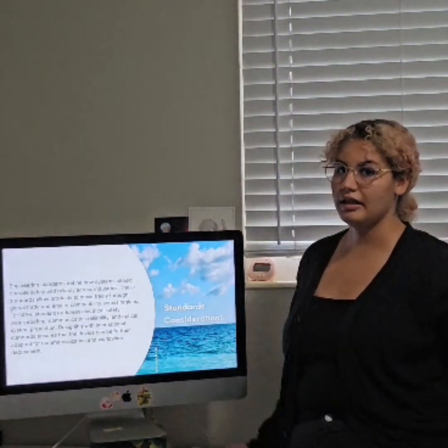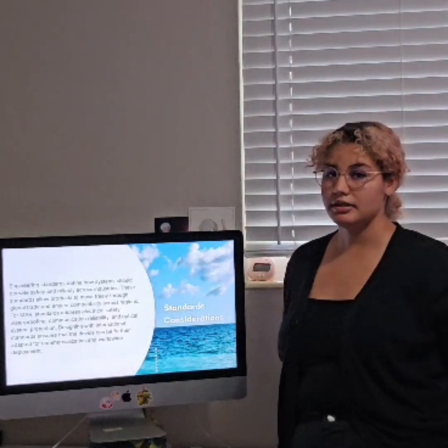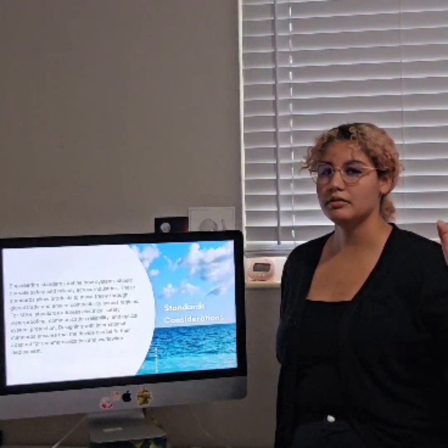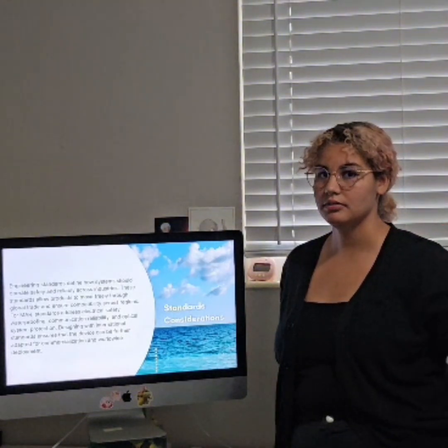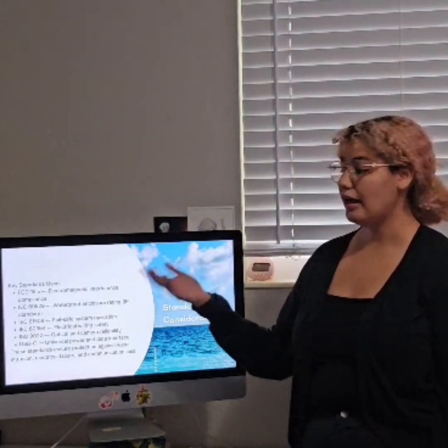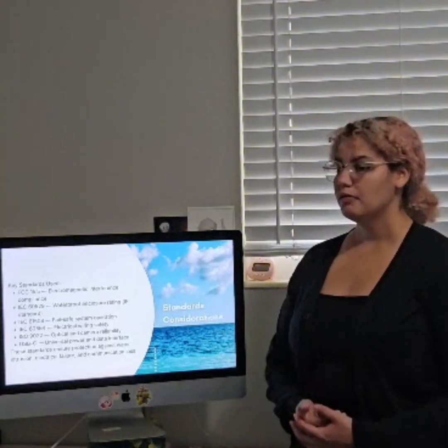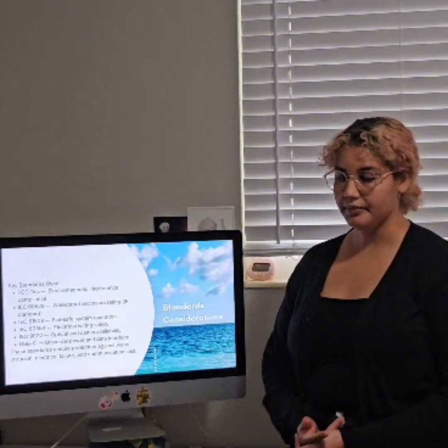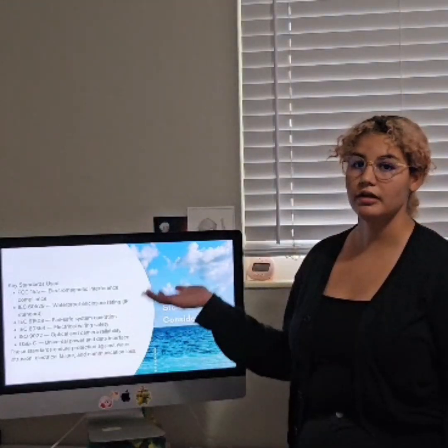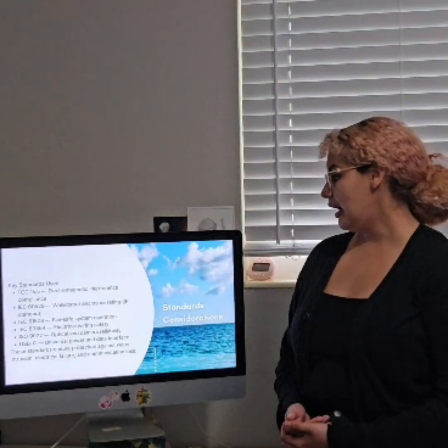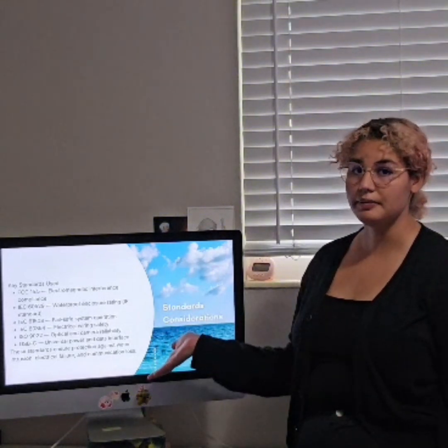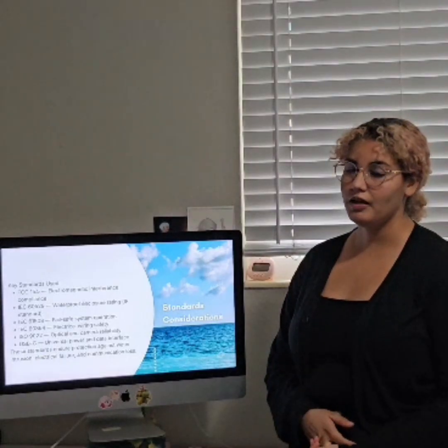In regards to standards considerations, the team has considered electrical safety, waterproofing, communication reliability, and optimal system protection for the project. Key standards include the FCC 15.5 for electromagnetic interference, the IEC 60529 for waterproof enclosure rating, the ISO 9022 for optical and camera reliability, and the Universal Data Interface USB-C.